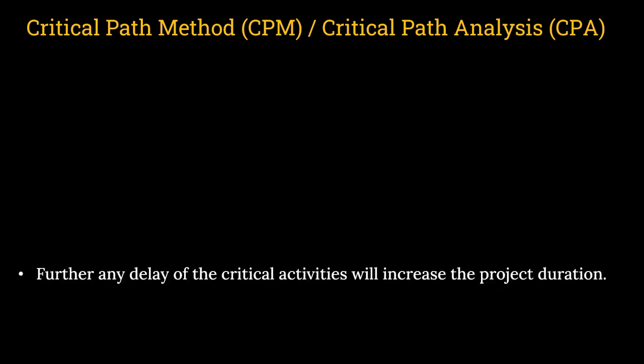Further, any delay on the critical activities will increase the project duration. The other way, if you are somehow delaying the completion of critical activities anywhere for some reason, then what will happen? Your project duration will be increased because that is the longest path of the project. Clear?